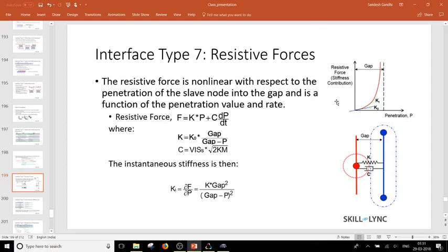So if you see any jump in that particular contact force, you can say that the penetrations for that particular time zone were too high, and that is exactly when the contact force jumped up. It tried to move those nodes out, and then it came back to normal. So it is very typical for the contact force to be very full of spikes.